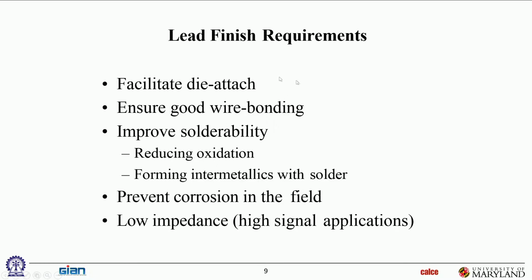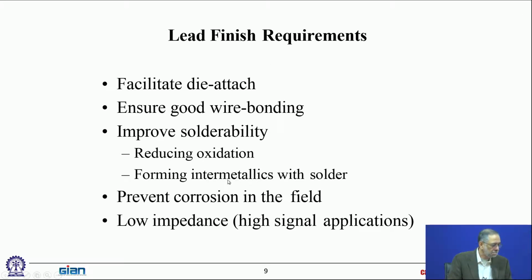Okay. And the purpose of that finish is also to help in forming intermetallics with solder. Again, unless you form the right intermetallic between the solder and the base metal, you haven't formed a joint. You cannot form too much intermetallic, then it becomes a brittle joint, but you have to form the right amount of intermetallic. So it's, again, a very complex optimization process. Not too little, not too much. So your reflow profile has to be carefully designed so that it stays above melt temperature just long enough that you form the right amount of intermetallic. Too short, you don't form a joint. Too long, you have too much intermetallic.